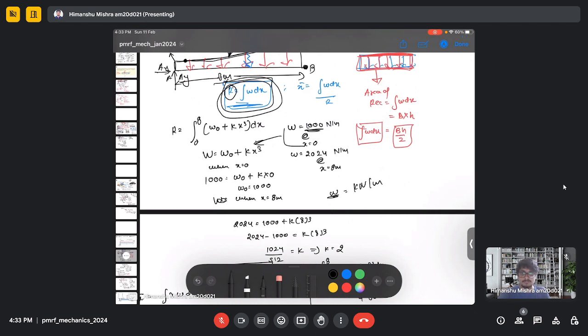Okay, then what's the meaning of per meter there? It's per meter, which means it's a force divided by length. So divided by length means a unit length force. You are actually specifying the force at a very specific point, and that's why you are dividing by the whole length. And if you change the horizontal length, that force will be changing.